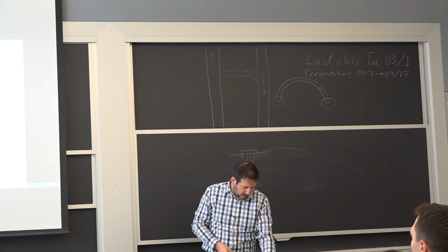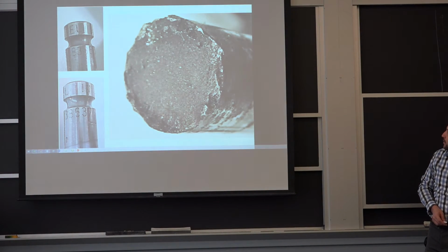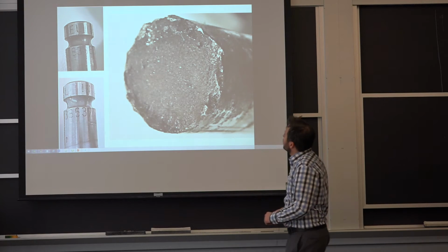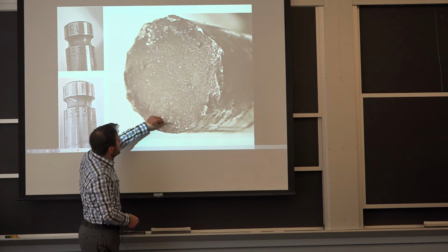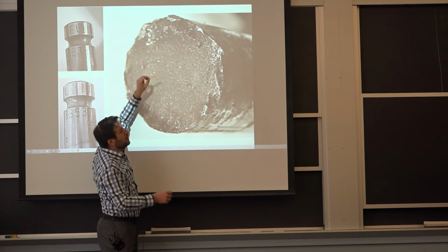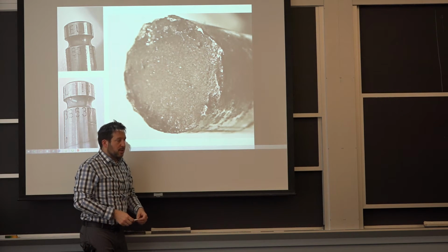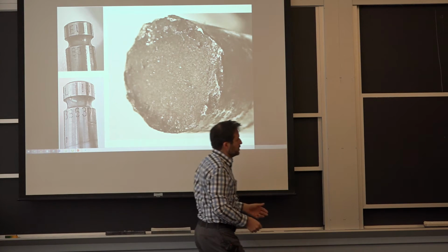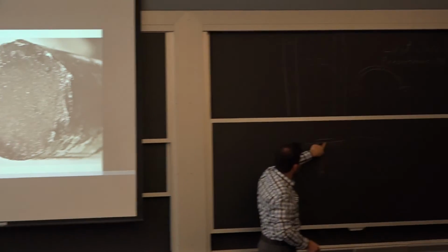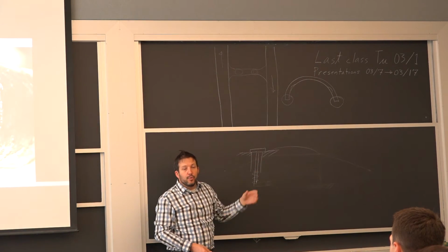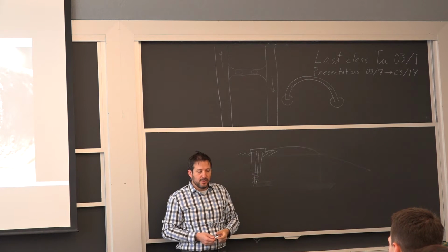What happened? You go and you look at that fracture surface, and it looks great here. The notes are already online, but it's a similar situation where this was a slow crack that went all the way to here, and you just had this little moon shape at the top at the final fracture. So what does that tell us? Because it's only supposed to be held in tension this way, we know it started essentially from one side and went to the other. So the valve was not sitting perfectly square on its seat. There was a little bit more load on one side than the other.